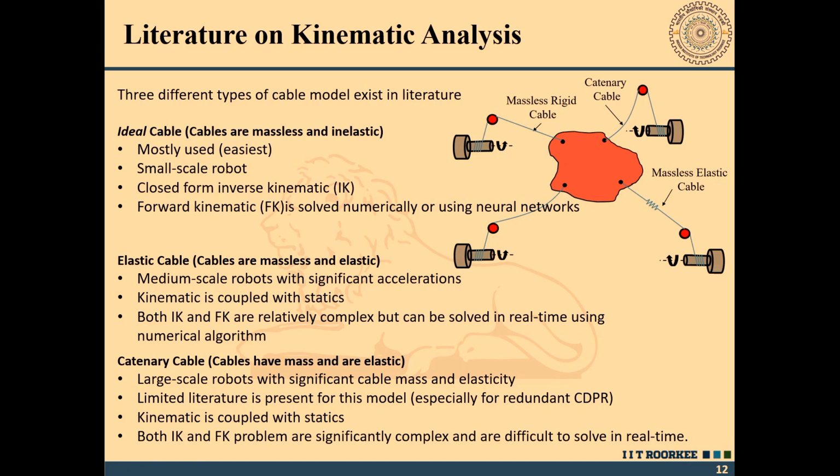For the small scale robot, this assumption is valid, and the closed form inverse kinematic solution is possible. Inverse kinematic solution in the sense that for the given position and orientation of the mobile platform, we could find out the length of the cable, how much length I have to extract or release for that purpose. So, the inverse kinematic closed form solutions are possible, and the forward kinematics is solved numerically or using neural network for this ideal cable.